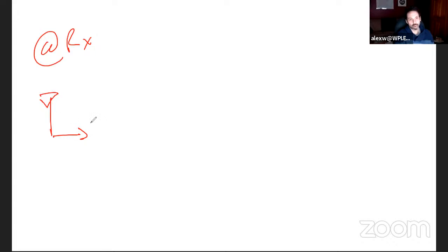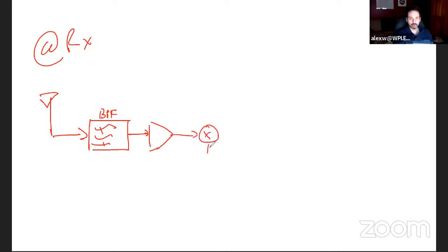So you receive the signal. This we exactly saw several class tests ago. So you bandpass filter out the desired signal band, BPF. We amplify it because it's probably pretty weak. That pretty weak part is what I'm getting to, okay? So we amplify it. Then we down convert it. And again, with superhead, we could be having multiple of these stages. I think that was class test 4 or class test 5 where we did this.